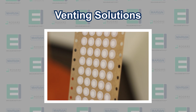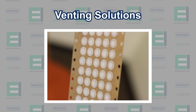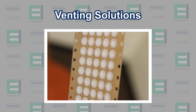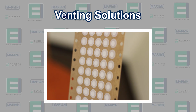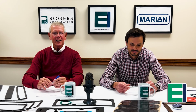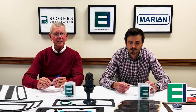For some types of enclosures, sealing them so well that they're airtight, dust-proof, and leak-proof can actually put the enclosure at risk. Those enclosures need to vent. So today, we're going to discuss a variety of venting solutions that may apply to your enclosures. Typically, the electronic elements within an enclosure create internal heat that, if not controlled, may cause the components to malfunction.